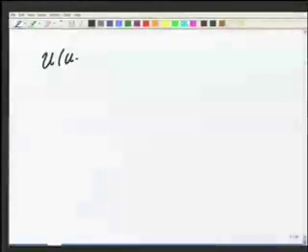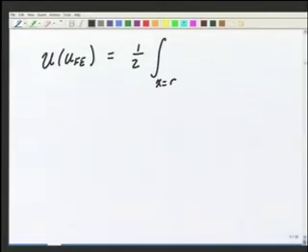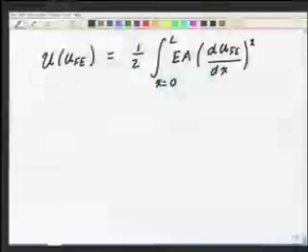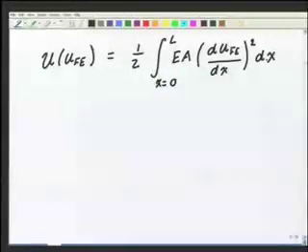Obviously, one question that will come to mind is, how do I compute the strain energy of the finite element solution? So if I look at the strain energy for this simple problem, it is equal to half integral of x is equal to 0 to L. I am writing it in a loose way because we should have taken summation over the elements. It should be EA (dUFE/dx) whole square dx. Now, what is UFE equal to?